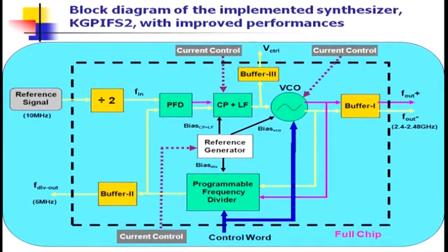The first thing I found is that the major phase noise contribution is coming from your VCO. Secondly, I have used a 5 megahertz reference clock, and if I look at the data sheet, this 5 megahertz clock contributes noise to the system.